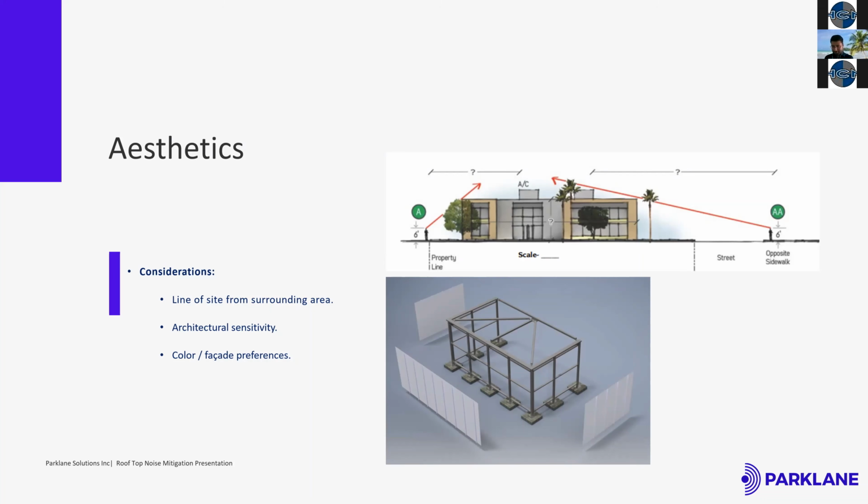I'll just chime in my 2 cents that obviously a higher velocity versus a lower velocity could create more noise. And then also, it's important to eliminate what I'll call turbulence. What I'm referring to is when you're transitioning from different sizes and have takeoffs and elbows and turning vanes, et cetera, it's best if you can follow SMACNA recommendations for transition sizes and degrees, et cetera. But Joe, I can talk to you further about that.